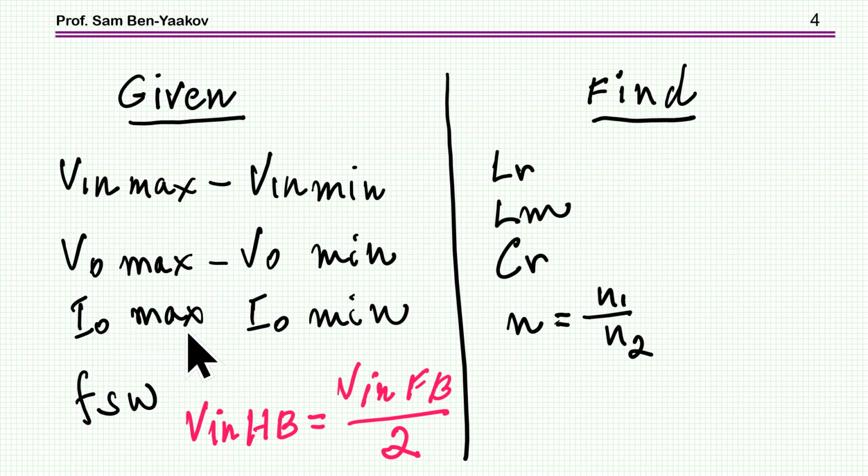And then we have a range of current that we might wish to have. And of course, we'd like to work at a given region of switching frequency, depending on the transformer, switching losses, etc. Now, the unit could be in a half-bridge or full-bridge configuration.